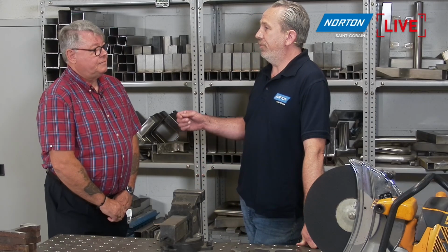So they find an ultimate temperature, stretch the rail to its ultimate point, which dramatically reduces the amount of rail movement in hot and cold conditions. Take the example of the UK: we can have -10 here and we can have +35 in the summer. We can have a huge range of temperatures throughout the year. So that minimises the distortion of that rail in those extremes of temperature. Absolutely. Okay, it makes sense.